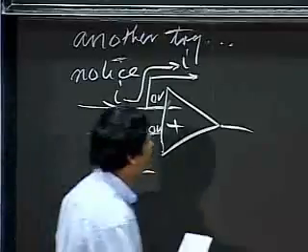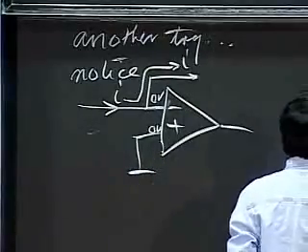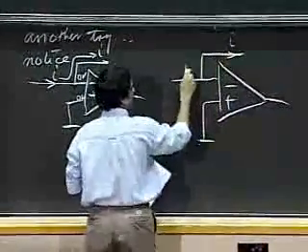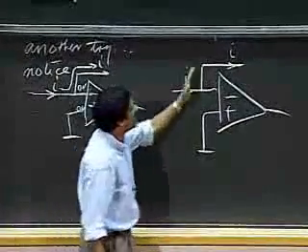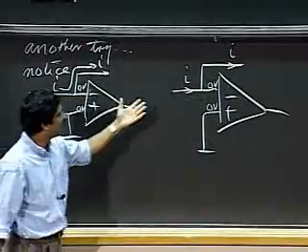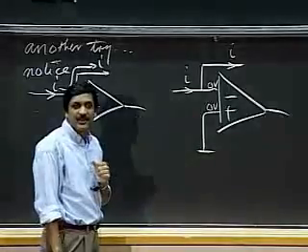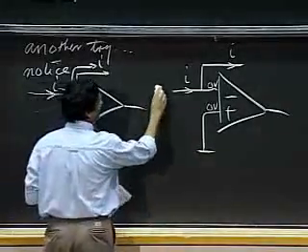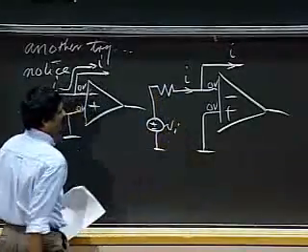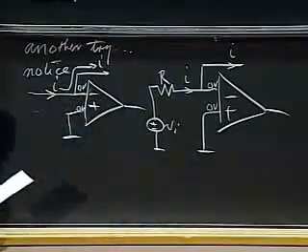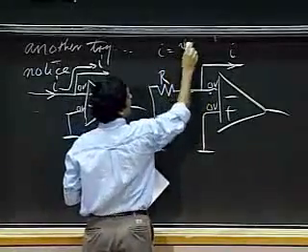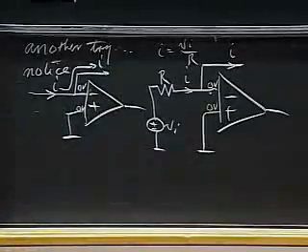So we're just one step away from the key insight. If I have an I coming in here, I going out there, and notice that, as I said before, this is 0 volts. So how do I get my voltage VI to become proportional to a current? It's simple now. All I do is put a voltage VI and put a resistor R out there. If I do that, then since this is 0, the current I is given by VI divided by R. I've got where I want to be.